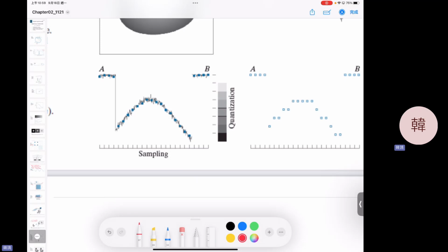For the edge component, they already have a large difference, so you don't need a lot of intensity levels to separate them because they are already different. That's another way to think about compression for image compression applications. You can have a very good image for human eyes, but you don't need so many bits to represent it because you cannot tell the difference. It depends on your application.